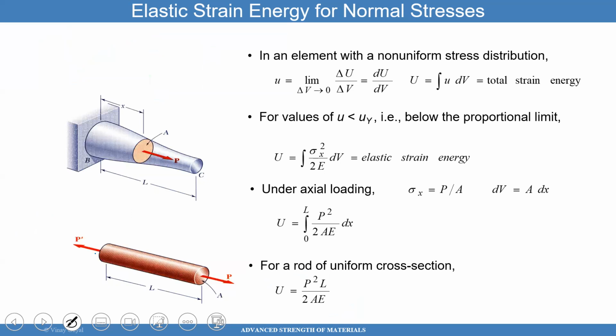But for the purpose of this class, we're going to assume it's a linear behavior where stress is equal to modulus times strain. And if I make that assumption, then the energy under the curve is sigma squared, the stress squared, divided by 2 times the modulus, which is the formula you see right here. And I derived it for you two different ways now. Does that make sense to you? Do you want me to derive it one more time so you can see it visually? I can do it quick. Some of you say yes, so let me just do it quick.